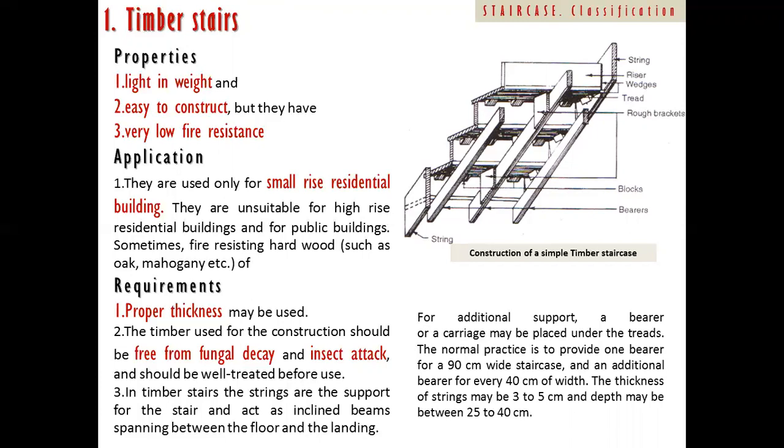Now, what are the requirements for timber stairs? Whenever we use timber for stairs, we need to have proper thickness. Timber used for construction should be free from fungal decay and insect attack.